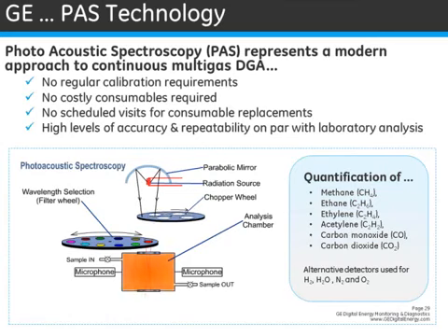Its ability to accurately trend evolving gases, evaluate the possibility of an active fault being in progression, and warn the user is second to none. IR-based multi-gas online DGA has really changed the face of transformer monitoring over the last 10 years.